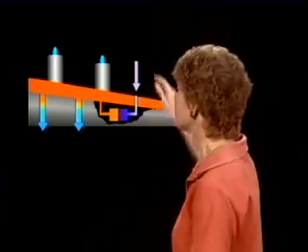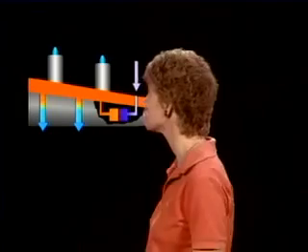Now, you've got one of two ways in order to prevent too much air from getting into the heater as the air pressure increases. You have a combustion air relief valve, or you've got a differential pressure regulator. Either one of those, it does not have to have both, in a combustion heater will keep too much air from entering the heater when the air pressure increases.